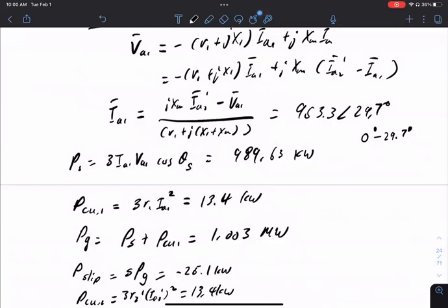Yeah, go ahead. You can have that by changing the angle. If this was not a negative 120 and the angle was smaller, you could reverse power flow. That's fine. That means we are not injecting reactive power, but you can inject active power going from the grid to the rotor. Then that will come out as PS. The power has to come out somewhere, and it will come out on the stator side. So you can cycle active power from the grid through the rotor and out of the stator.